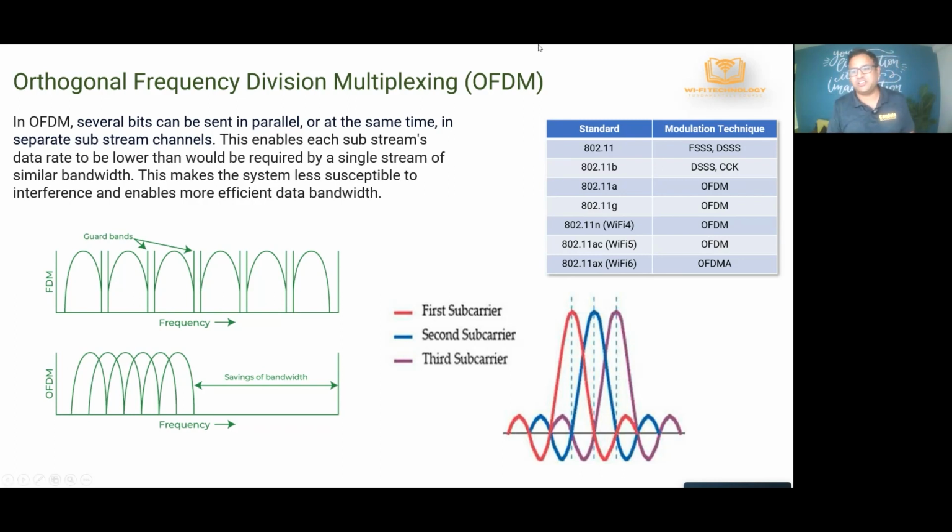And that is the reason why we use those methods in 11n, 11ac, and 11ax and all of that. And we'll go into more detail about OFDM and OFDMA in the coming sessions. So how does OFDM work? What OFDM does is it says, okay, this is the amount of spectrum available. Let's assume that you have a 20 megahertz channel. So I have 20 megahertz of frequencies available for me to transmit. Let me break them down into smaller chunks, or subcarriers.